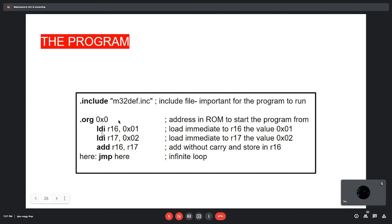Next we have the LDI. It stands for load immediate. So load immediate R16. See, at the very beginning I showed the registers of the microcontroller: R0, R1, R2, the general purpose registers up to R31. What we are doing is storing one number, which is 0x01, actually 0000 0001, eight bits. We are storing this number in the R16 register. You can choose this yourself: R16, R20, R31.